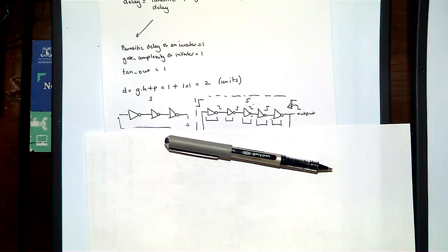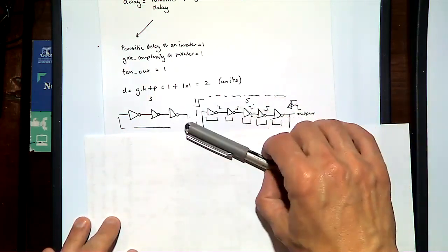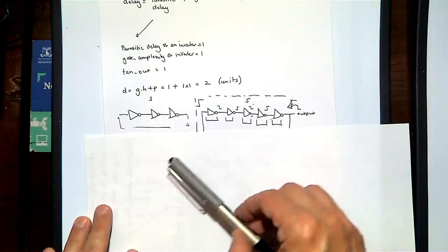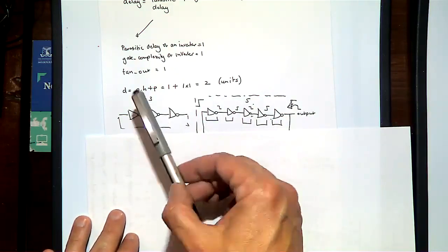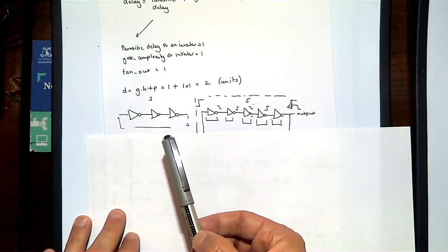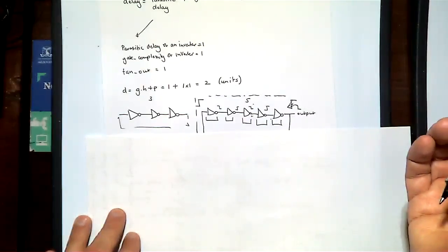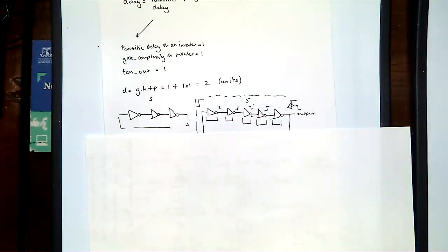So one of the problems is you don't really know, if you're producing a chip, how much of the good stuff it has actually gotten. One of the tricks you can do is build a couple of ring oscillators on there. By looking at the speed of the oscillator, you can work out which corner you're at. So if you're on fast, you would expect the oscillator to operate at a faster speed, right? I guess you guys don't know about corner skews and things like that? No? All right, let me forget about that.